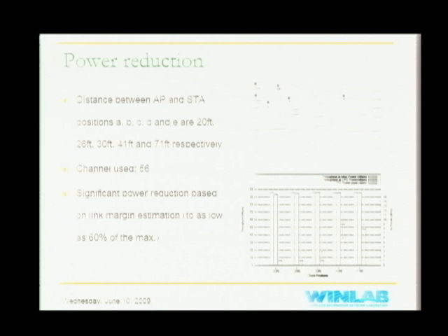So here we can see from the graph, based on RSSI estimation, the y-axis on the left represents the throughput and the y-axis on the right represents the transmit power used in dBm. The maximum power, which is default, I have not shown in these graphs. So the first bar represents the throughput with maximum power, which is 15 dBm, and the second bar shows the throughput with the TPC power. Let me just call it that, TPC power that we calculated.